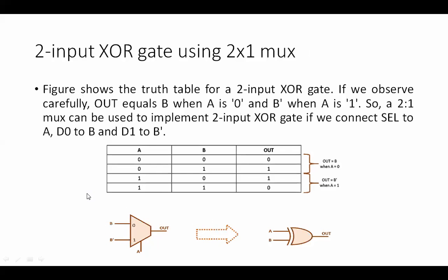Okay. Next with XOR, if it is same 0, different 1. So XOR is a very important gate which can also act as a comparator. When I say comparator, it can compare two values. It can see if the levels are same or not. Based on your output, you can decide that A and B are same, but I do not know if it's 0 or 1. That's the only downside.